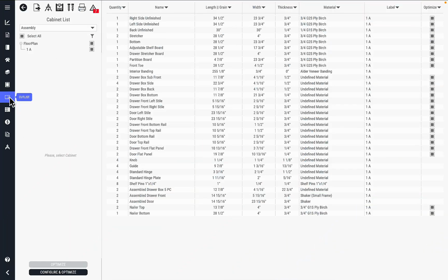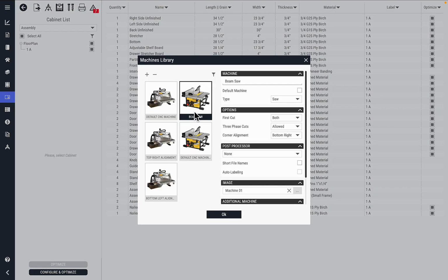We have some exciting news on the machining side of things as well. This update marks the first time we've integrated ourselves with beam saws, which are saws that use NC code to control and cut the parts. So if you go to a machine, make it saw type, and you'll notice that you can assign a post processor now called saw CP out PRV. So right now we're outputting to CP out file format, which is compatible with a wide range of beam saws.